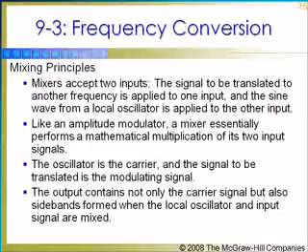The signal to be translated can be a simple sine wave or any complex modulated signal containing sidebands. The local oscillator signal usually appears in the mixer output, as does the original input signal in some types of mixer circuits. These are not needed in the output and are therefore filtered out.